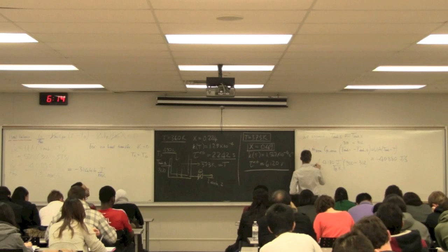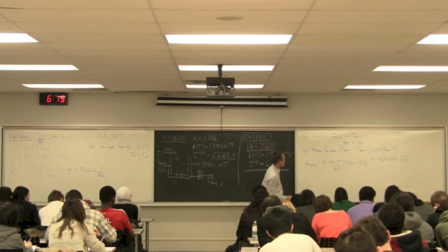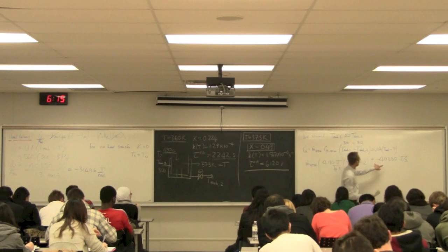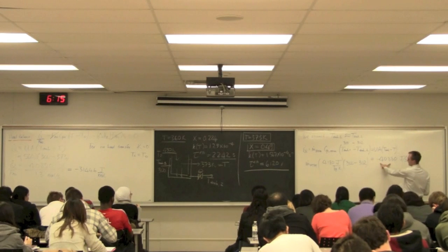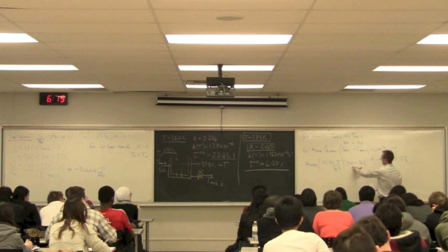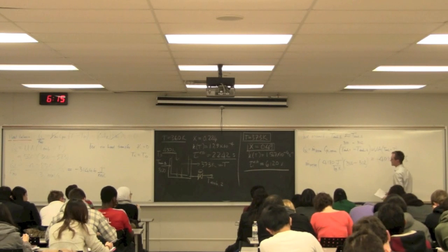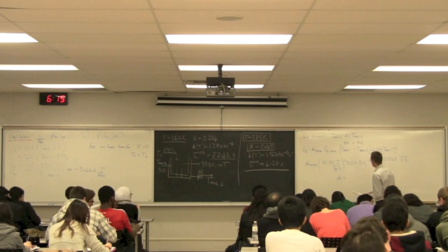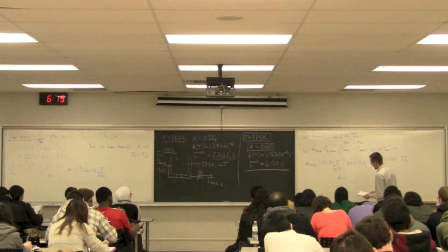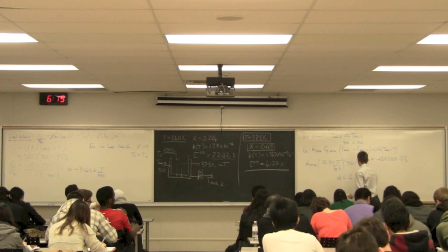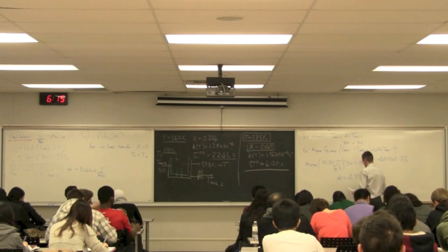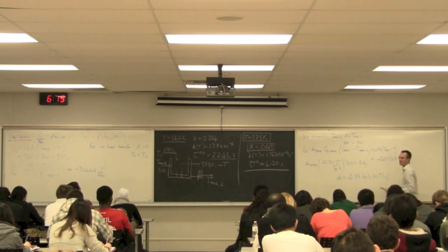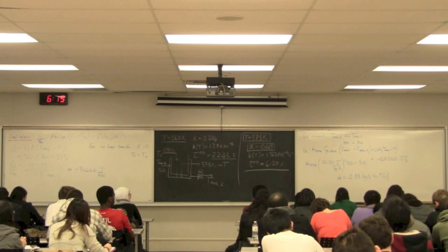For our heat transfer medium, in kilograms per second, the units will cancel and get us kilograms per second. Notice there's a negative heat on this side because we're removing heat from the system, but this is also negative over here, since our ambient temperature leaving must be warmer. So it is consistent, and we won't get a negative mass flow. That's good. My heat transfer medium flow rate for a 2 Kelvin rise corresponds to 4.88 kilograms per second, or about 5 liters per second. That's a phenomenal flow rate. That's really high.